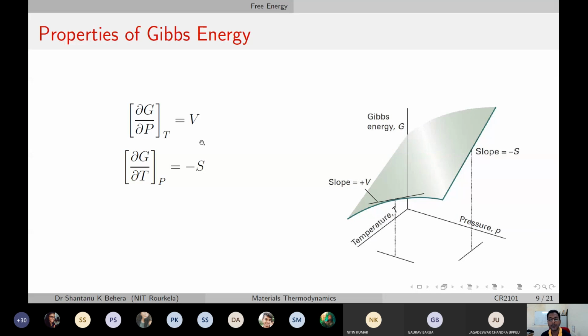And if you want a physical representation of that in the thermodynamic coordinate space, you'd see something like this. This is the variation of G over changing pressure and changing temperature, right? This is what it is. So this talks about the phase stability of the material system, or a combination of materials.